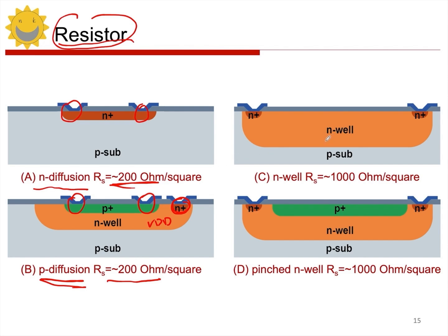Now we can also look at what else? N-wells. We can use N-wells to form resistors as well. So I can draw an N-well and then inject N-type material on both sides to connect it out. This way we form an N-well resistor. The square resistance of the N-well can be quite large, reaching up to 1000 ohms per square. And then what else can we do? We can also have this pinch effect, which is a pinched N-well. So what does pinched mean? It means that I add a P-type doping on the surface of this N-well. And then I add a P-type injection. And then this...